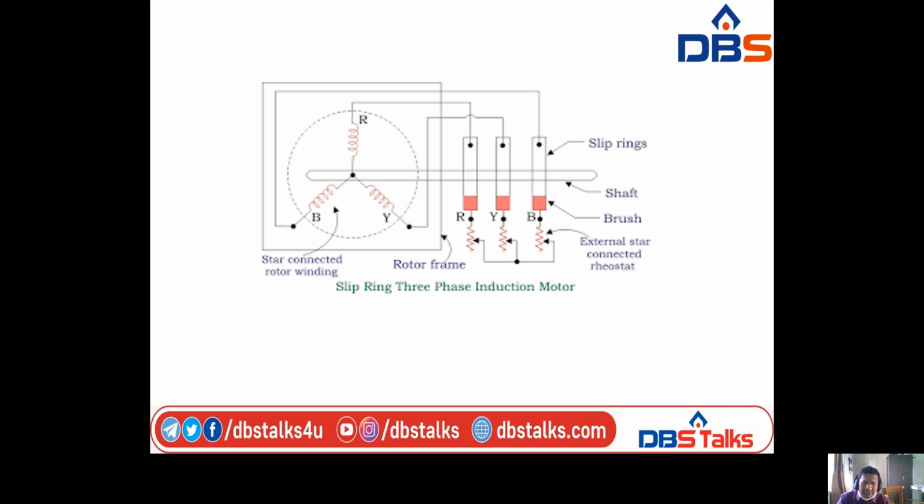And this rotor winding may be put on the motor shaft. So the end connections of the 3 phases R, Y, B are connected to one end of the slip rings, and another end of the slip rings may be connected to the brushes. So now the brushes are connected to the 3 phases of external resistances, and this external resistance is also connected in star. Now what is the purpose of slip rings and brushes? Nothing but to collect the current from the rotor winding, the rotor 3 phases.